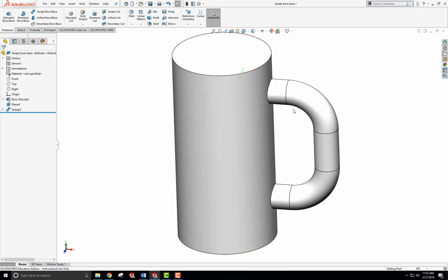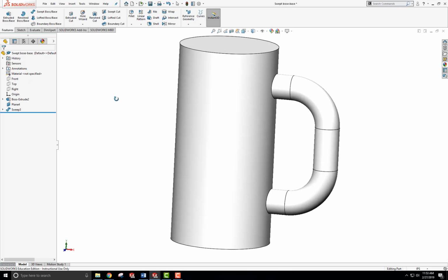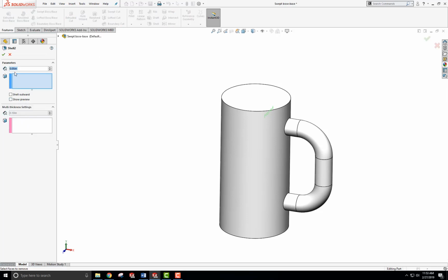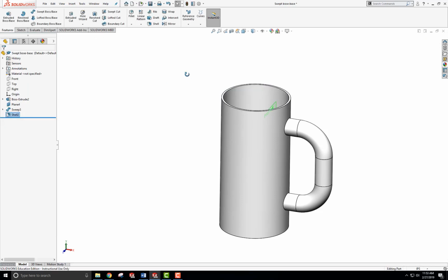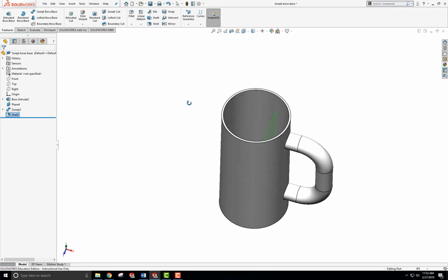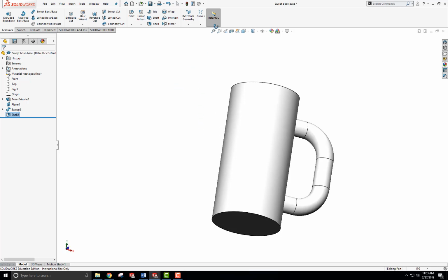And even a reminder, even though you see these lines here, these are transparency lines, and they're going to disappear when you render or turn them off. Okay. Next quick tool I want to talk about is the shell command. Shell command is here, and you can set the thickness of the walls, and basically choose any surface. And check mark it, and it basically cuts out whatever it sees and creates a 0.05 thickness shell of whatever you have there.